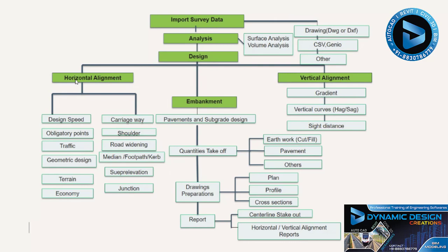In rural roads we can go beyond 4% as per the codes, because vehicle speed is very high. But when it comes to wind and solar projects, we allow up to 20% vertical slope. It is not in the code, but it is ground reality. They are designed based on the vehicle configurations.